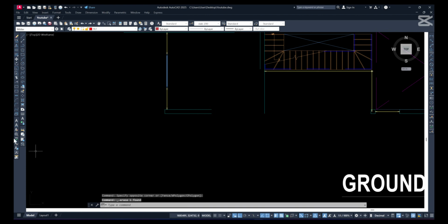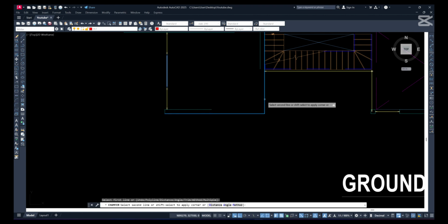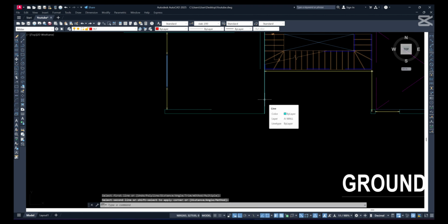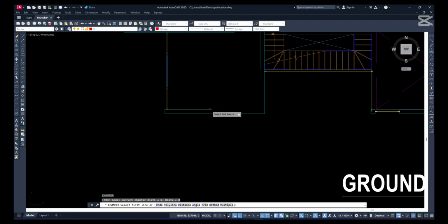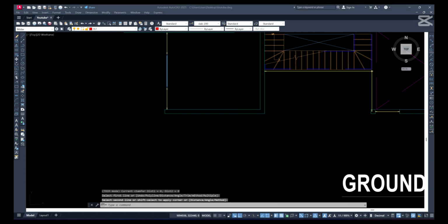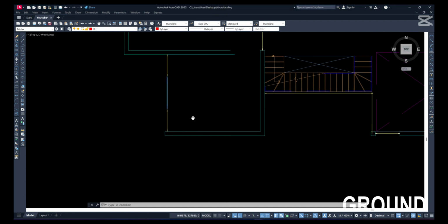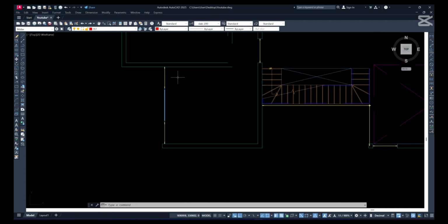So I'm checking the distance, that's the span of each panel. If it's above, say, 5 meters, 6 meters, 7 meters, 7.5, it all depends on the structural engineer's risk appetite and level of experience, like I said before. But I'm just checking it so that you guys can see what I'm doing.